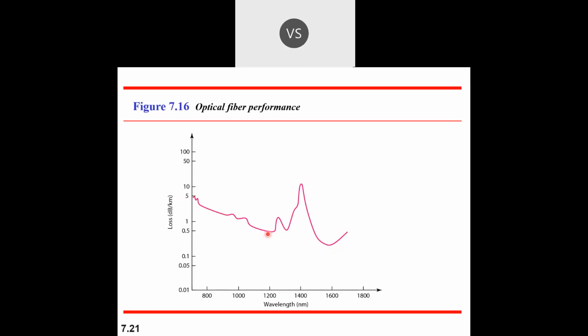For some range, I can say 1600 nanometer range, it means the frequency is 200 terahertz. It's not a kilohertz, it's not a gigahertz, it's not a megahertz. It's a terahertz, 10 raised to 12 hertz of frequency. So with that speed of light, you can achieve that transmission speed if you're using a fiber optic cable.